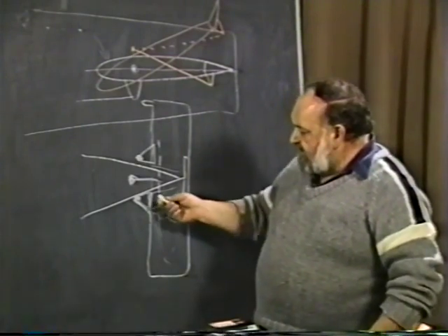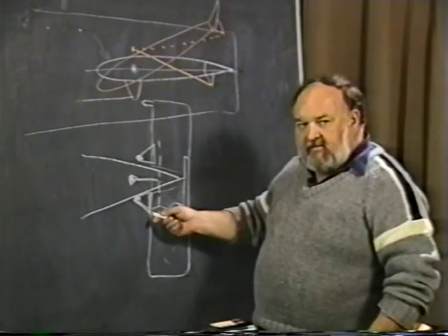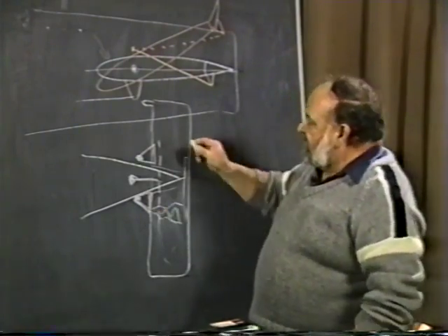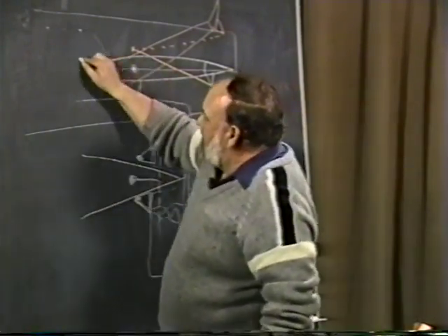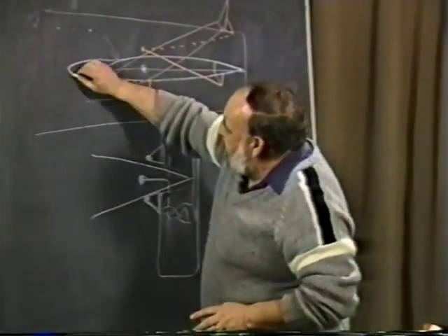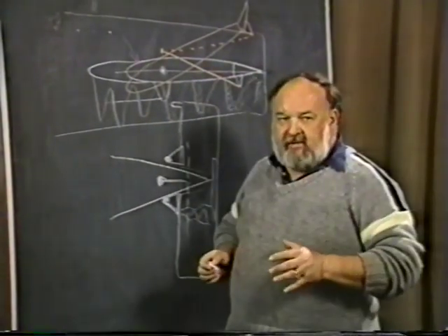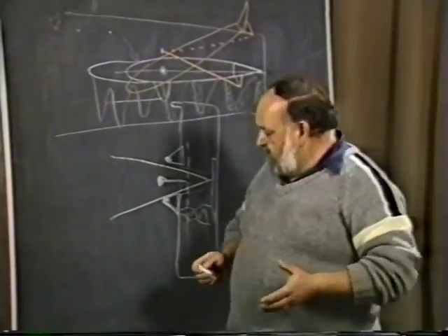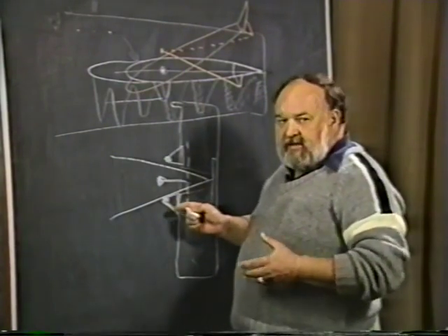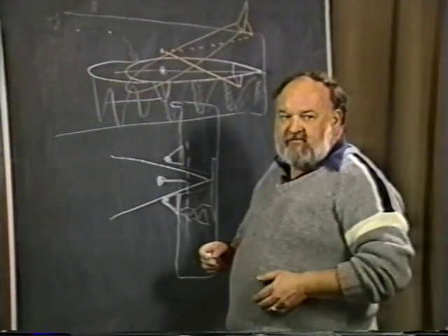This has that advantage, again, that you can put your mass balance into it, you end up with a nice aerodynamic vortex to it, and then even from a side view, when you have this extended surface sticking out in here, from a stability standpoint in spin, this area up against the side of the fuselage is a very powerful area to giving you spin stability. So by doing this one aspect of the thing, we had 3 or 4 things that helped us out on it. It's a good method and a good effective way of doing it.